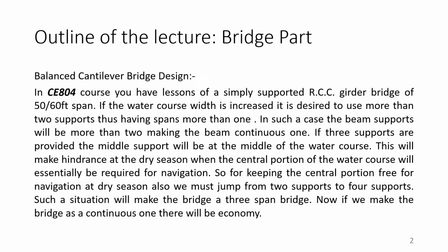In our country, the river bed is mostly alluvial soil, and the stability of the river bed is uncertain, and that's why we are very scared about support conditions and settlement and other things. So we will try to make the bridge a simply supported one with cantilevers.